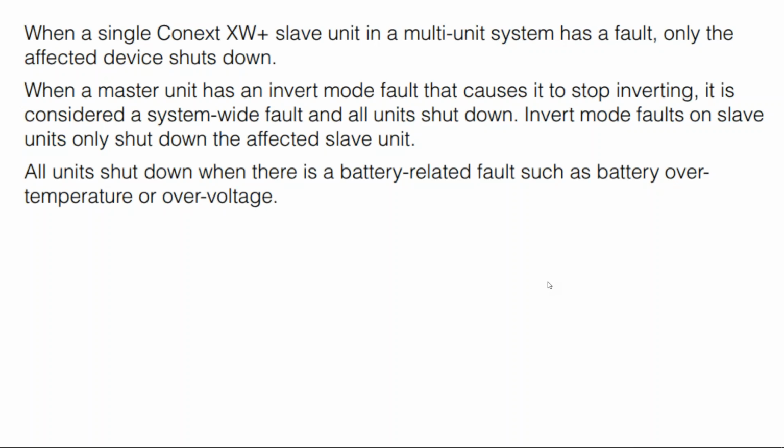So when there's a power failure, the frequency of the grid changes. And so your higher end battery inverters will change the frequency of your home from 60 hertz to 59 hertz, and it'll click the batteryless solar arrays off.